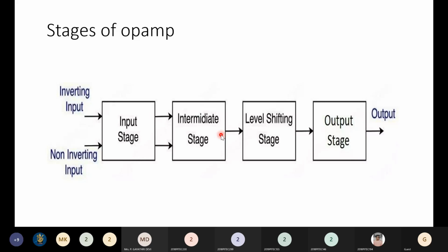And therefore, what will happen when I give an AC signal? My AC signal will get amplified here, and along with that, a small amount of DC will also get amplified here. So what will happen when DC gets amplified? From where will we be getting the DC first? I'm giving an AC signal here, but still, you all know that for an op-amp, we are providing the DC biasing voltage, that is plus 15 and minus 15. We don't know V plus and V minus. So it is a DC bias voltage. So this bias voltage will be there inside the circuit.